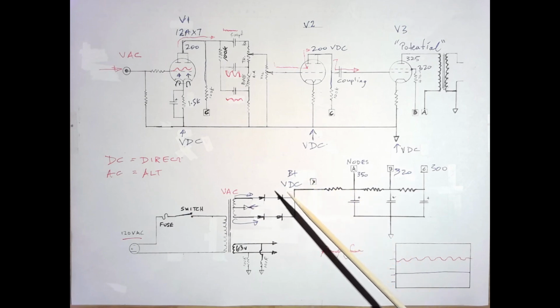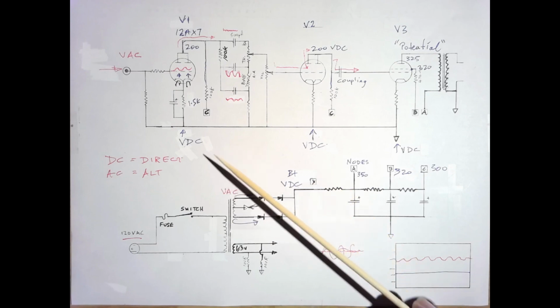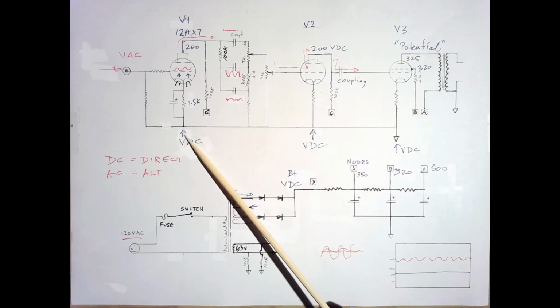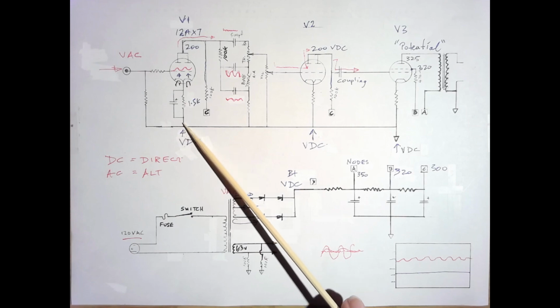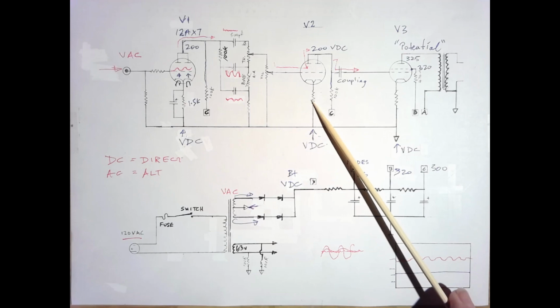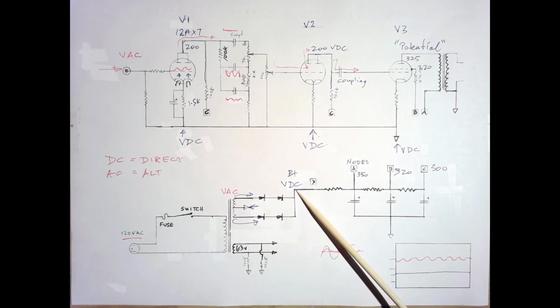But actually, we finally figured out that DC current flows in the opposite direction than we initially thought. That is to say, it flows from the ground up through the tube toward the plate. So our current is actually going from the chassis to the center tap, through the center tap, cycling around through our rectification, whether it's tube rectification or diodes, and turning into a DC voltage.